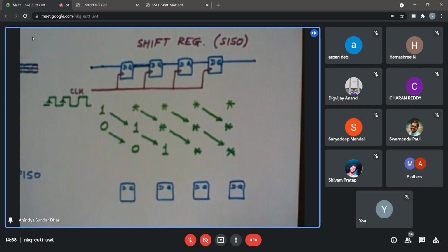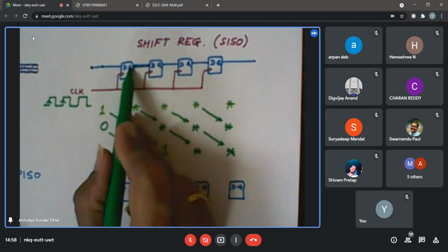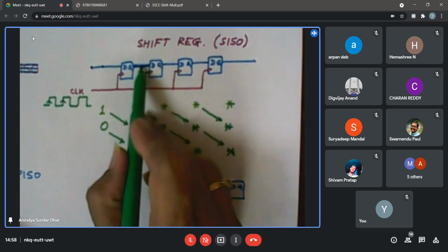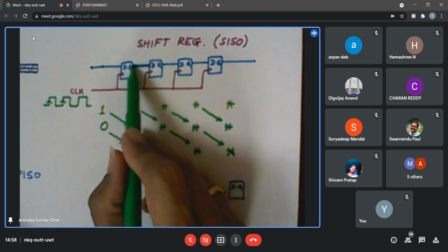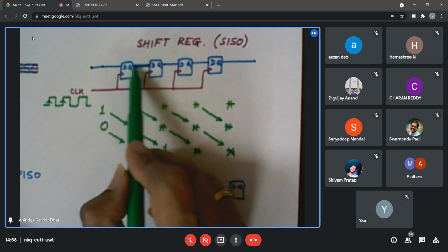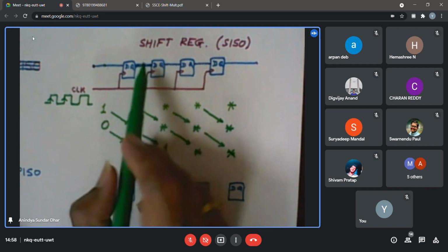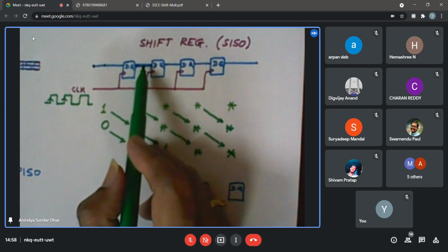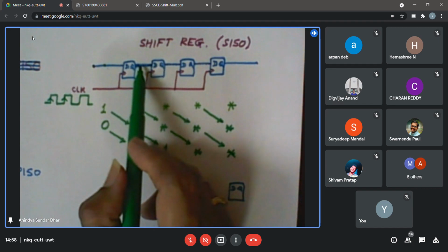Yes. So the problem is that if from this side there is an output Q, it can either be 0 or 1. And if I connect another line to the same D input, and if they are not matching, suppose the output of this one is 0 while I am trying to make it 1, then there will be, I think the term he has used is collision or something like this. Sometimes it is called a contention, logical contention. So one is trying to pull it down to low, and the other driver is trying to pull it to high. So there will be huge short circuit current flowing, some of the devices get damaged and so on.